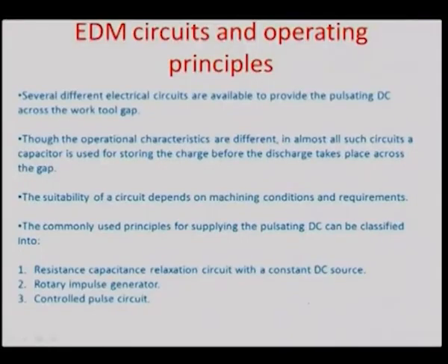Now, we will come to a very different aspect of the problem. We are talking about a case where we have to keep on feeding voltage in sparks, and the frequency at which energy is being applied should also be optimized with the frequency at which the spark is formulated. Otherwise, we are losing energy if we give a continuous supply of energy and let the process follow by itself. The point of time when the spark is formulated should match the frequency at which the energy is being supplied. So, the packet comes and gets delivered, and then another packet gets delivered.